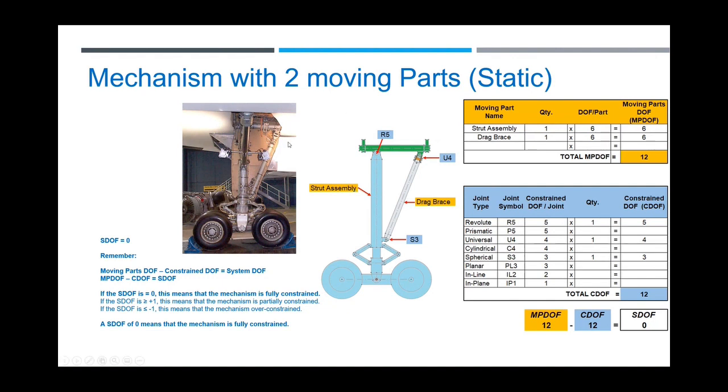Well, one of my favorite landing gears, which I made, can you guys see this on the screen? Yes. Okay, this is the Concorde landing gear, and what they did was to keep it from this, what they call the forward backstay, the drag brace. When they assembled this strut and the drag brace, they don't bolt it together. They use joints. So basically, the math is this: this is the vertical strut, and it has a revolute joint here, and then here it has a universal joint. And down here is a spherical joint. Well, actually, I just made a spherical joint because it can actually rotate, but just stay with me here.